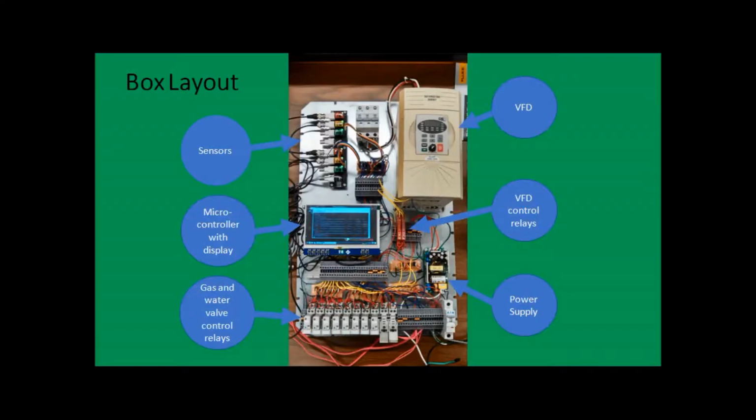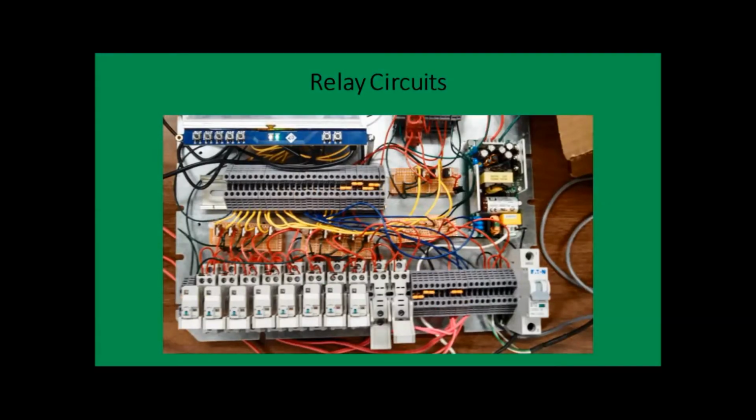A water pump is also commanded when to run and at what speed by utilizing a variable frequency drive, or VFD. The VFD is controlled by gating command signals with control relays. These command signals extend from water level sensors used to determine whether the algae banks are full and empty. The microcontroller receives and stores all sensor data and transmits all command signals to their respective control relays.